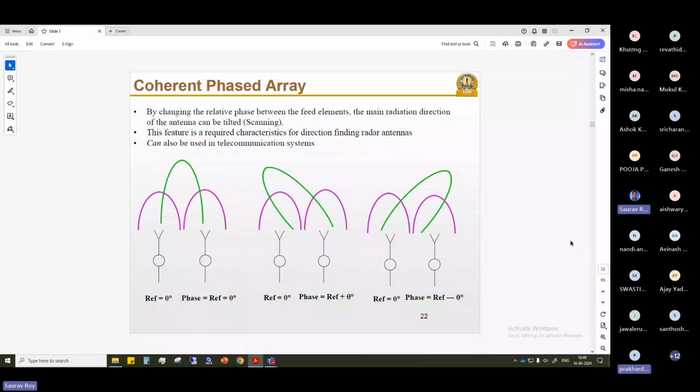As we use very high frequency, the path loss increases. So we cannot use one base station antenna for 5-10 kilometers. It does not make sense. You will lose a huge amount of power. So generally, in the current scenario, people use very small cells. Cells are where the signal will be covered from a base station. You use a very small cell, and the antennas will have a very pointed beam.